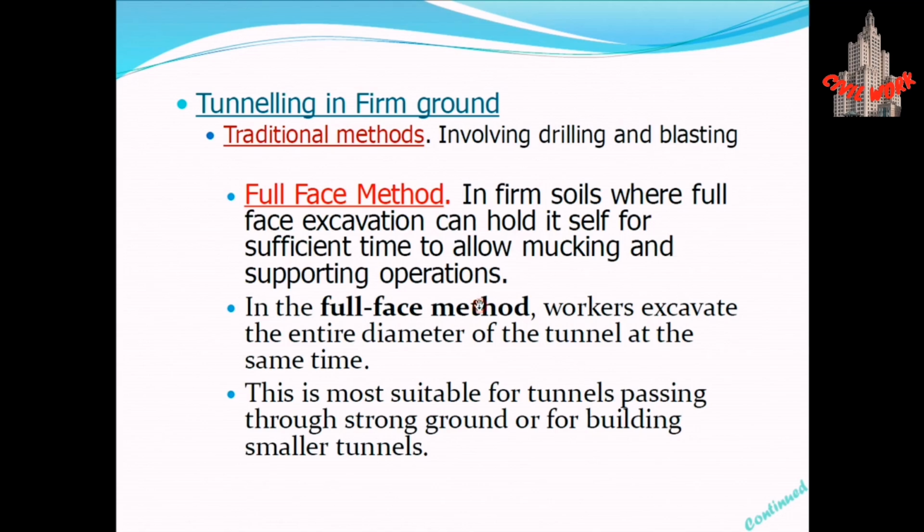We don't have to pay too much attention towards the safety during the excavation, because we know that the ground is firm, and then we only need the shotcrete for the lining in the tunnel after the excavation. The full face method is generally applicable only in firm soils where the full face excavation can hold itself for sufficient time to allow mucking and supporting operations.